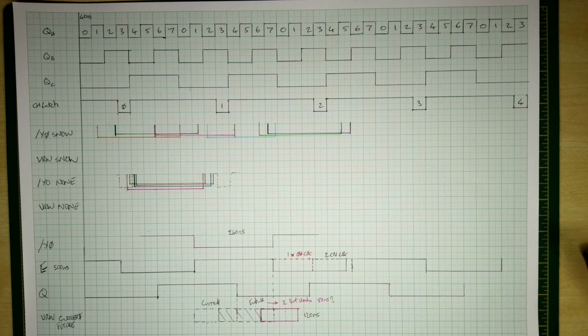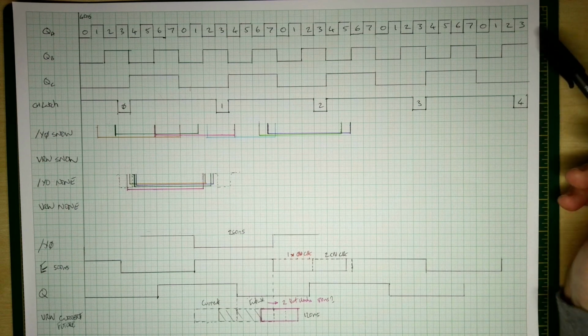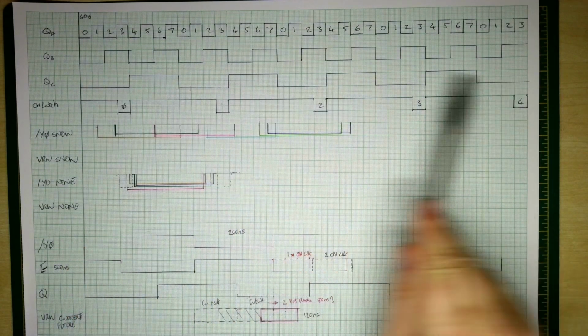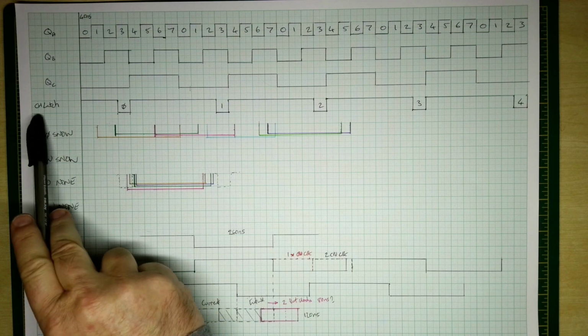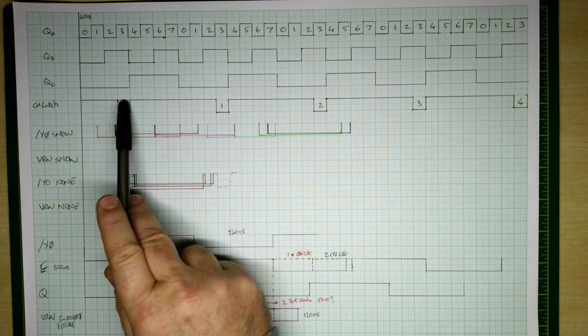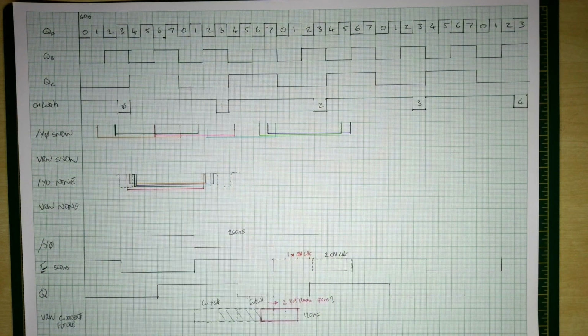But what this basically shows is the QA, QB, QC signals which are coming out of the video divider that produces the various clock signals. So the QC is in fact the CRTC character clock, and the character latch is the signal that actually causes the character and color attribute latches to load the data, and also the equivalent latches for the high resolution 2-color graphics. Then these are the signals that, from all the analysis of the logic analyzer output, caused the interference.